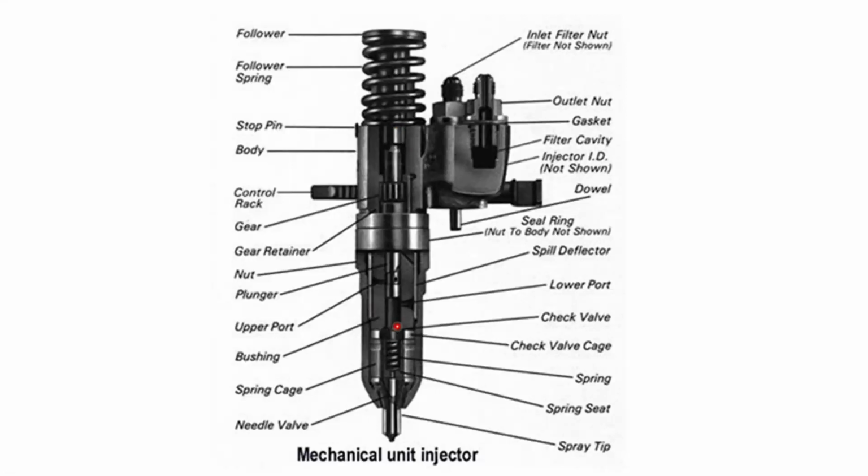It creates friction, and we are out to reduce that. It needs lubrication and cooling. To provide that, fuel is supplied through a small hole here as leaked fuel coming out from there. It won't go easily; it has to come through this way. So once this valve opens, only then does fuel flow through this.